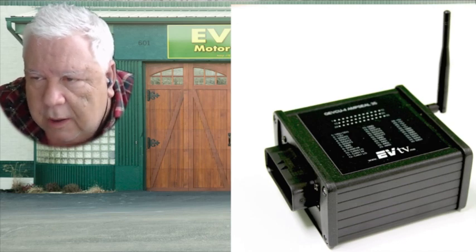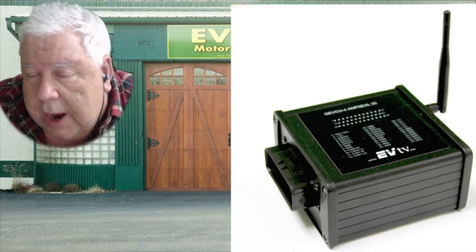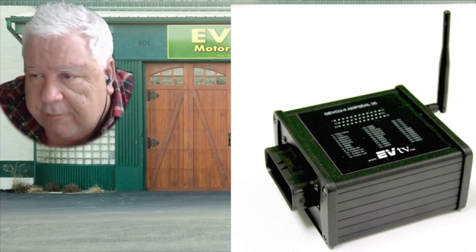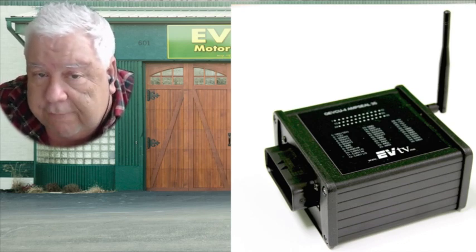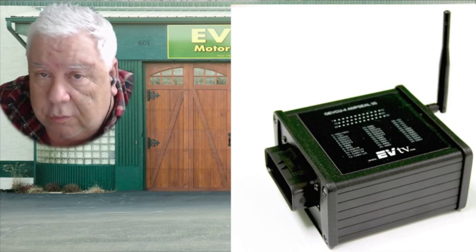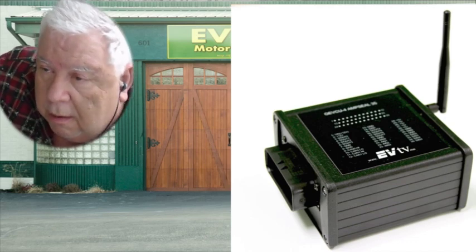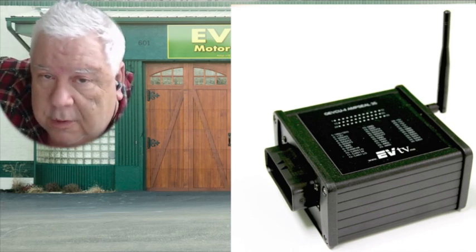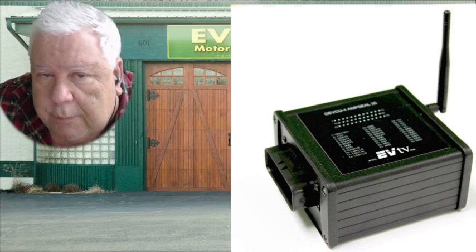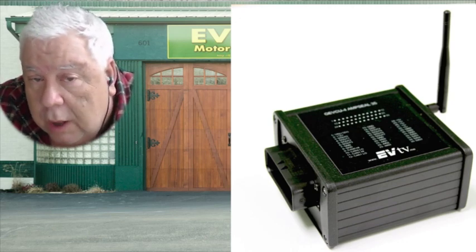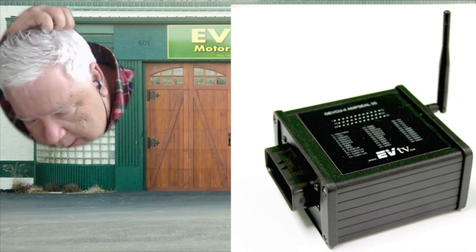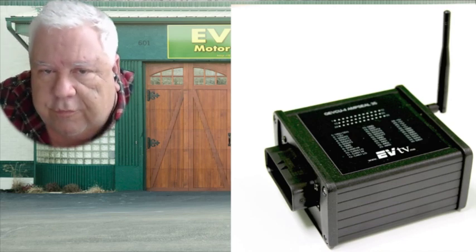And we've made the web interface a little more informative and interactive, and added features to drive cooling fans based on temperature, to drive brake lights based on regenerative braking, and pre-charge procedures to run a couple of relays to pre-charge your DMOC 645 or other inverter. And so we continue to work on the software.